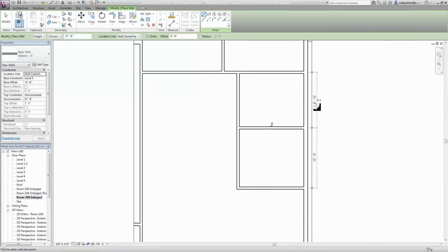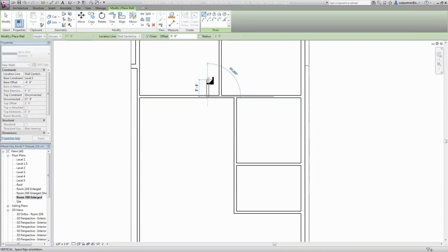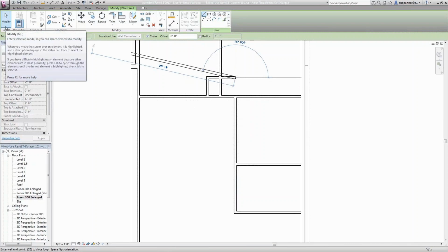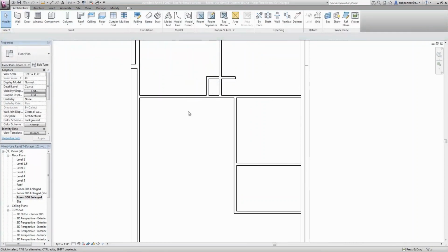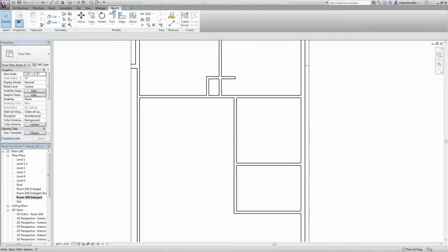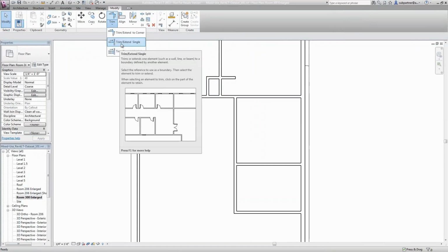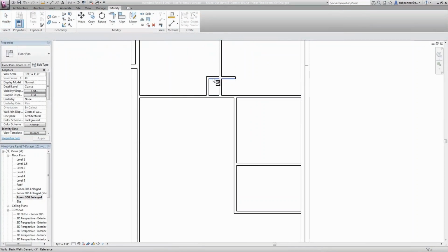using familiar stuff like you are used to in CAD. So drawing walls means not drawing only lines, but you see that the system is cleaning up the corners, having extension possibilities, etc. Very similar, but in a minute you will see what the result is. So you have, let's say, trim and extend functionality. Similarly to AutoCAD, clicking objects which you want to trim, and which will be the limit of the trimming, and voila, done.